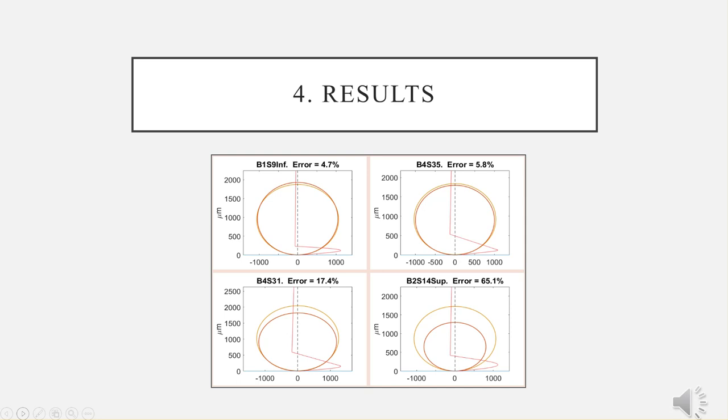In the present slide, we can see 4 different tests that were simulated by making use of the complete model previously discussed. In each of the figures, 3 items are drawn. The yellow ellipse represents the bright elliptical region of the fracture surface that was measured experimentally. The orange ellipse represents the shape the crack had just before transitioning from an embedded to a superficial state, according to the numerical simulations. Finally, the red curve sketches the residual stress profile in each case, providing some insight of the length scales.